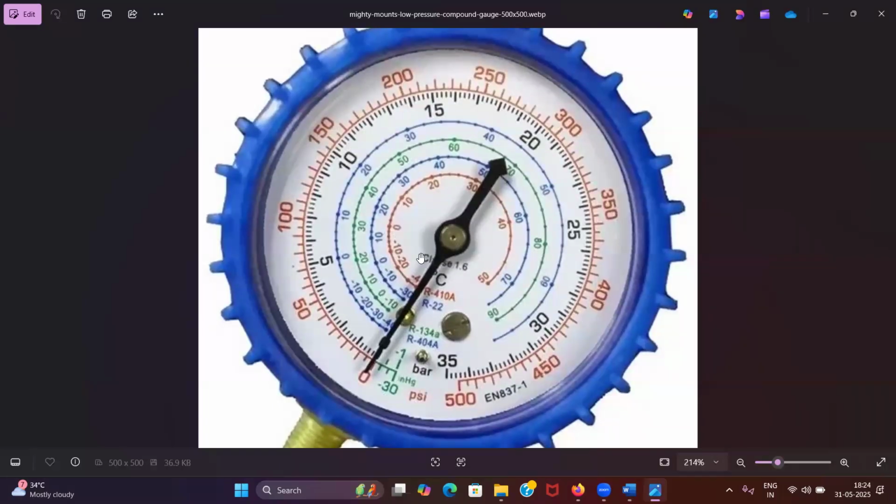How to differentiate between the compound pressure gauges of suction and discharge? Sir, suction will be in negative. Suction will also have a negative value. You can see -30 is written here and -1 here, 1 bar. That will be the suction pressure gauge. These questions are asked in cross questions. Like how will you differentiate between a suction pressure gauge and a discharge pressure gauge of a RAC system? So the suction pressure gauge will also always show readings in negative, vacuum also. Is it clear?